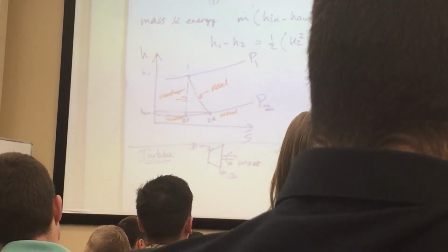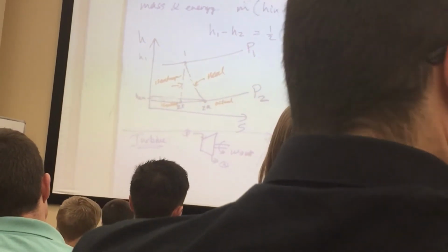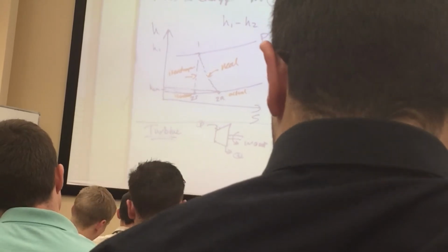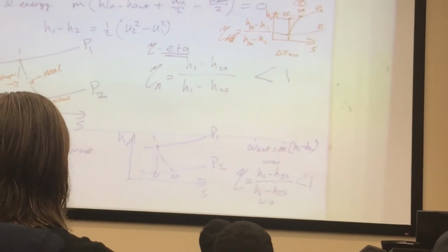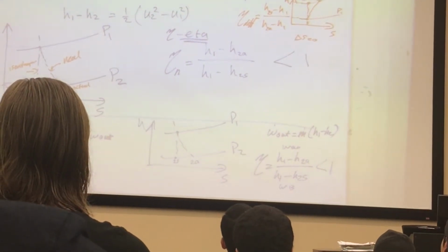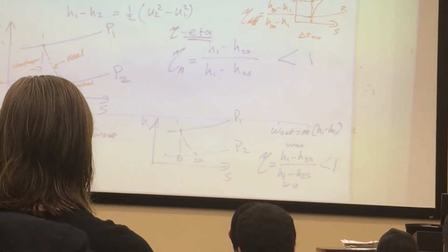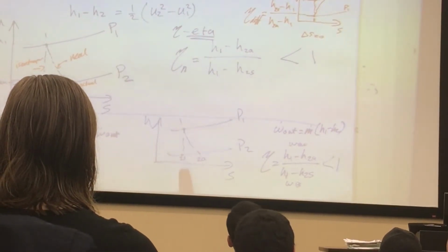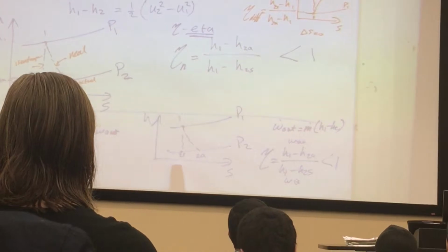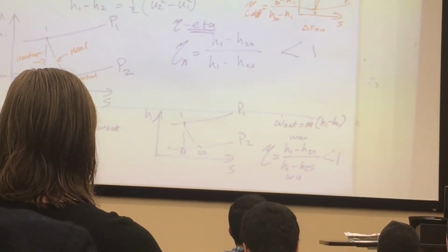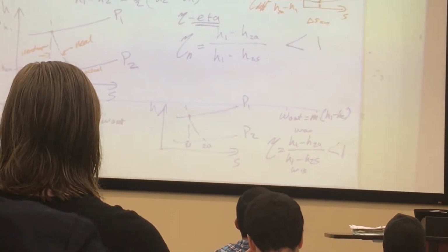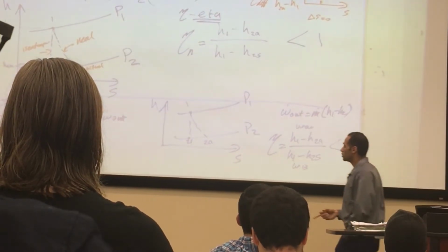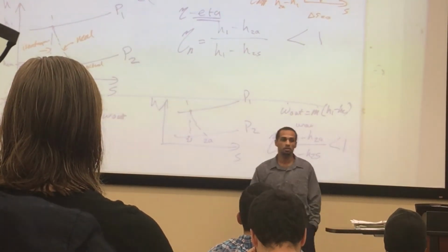So a turbine, what happens through a turbine, the flow expands across there and produces work. So accordingly, if I'm expanding, then I'm going from a high pressure to a low pressure. The isentropic process, meaning I don't have any losses inside, it's a 100% efficiency system, I'm going from 1 to the 2s isentropic process. However, that's not the case. You have turbine blades, you got boundary layers that are going on, you got tip separations inside.